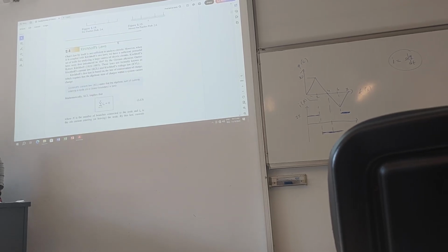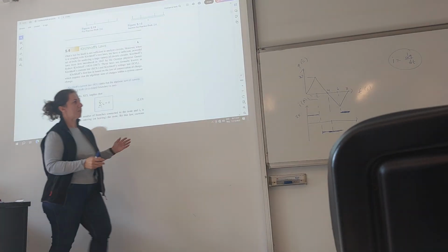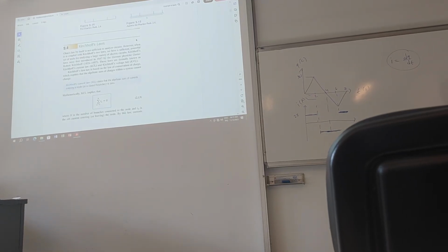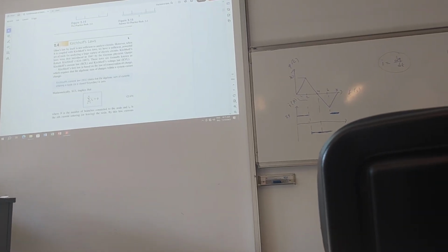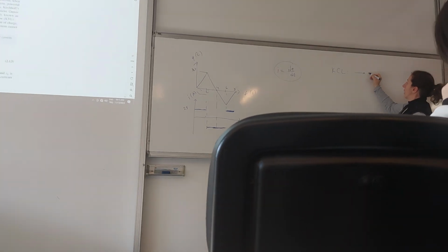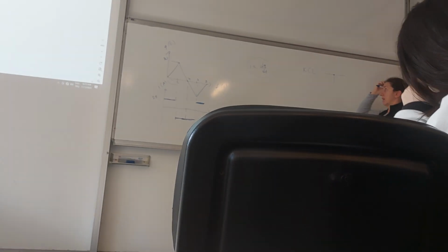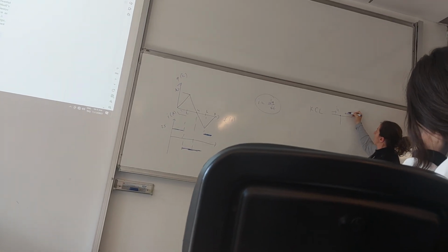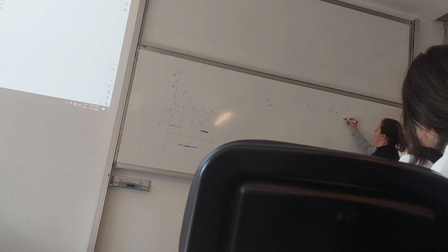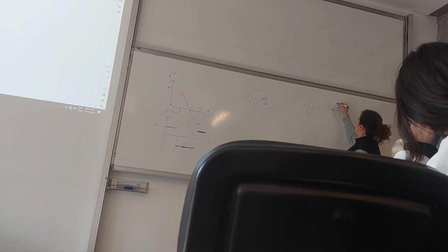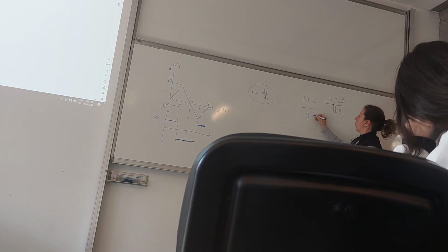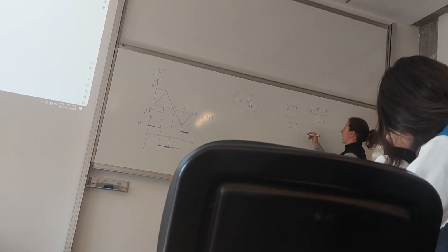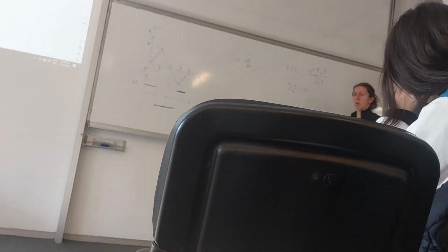We have discussed the Kirchhoff laws, which we are actually using all the time. The first one was Kirchhoff current law. If we have a node and there are different currents coming into that node or leaving that node, Kirchhoff current law states, if this is node A, if I calculate all of the currents at the node A, the sum should be 0.